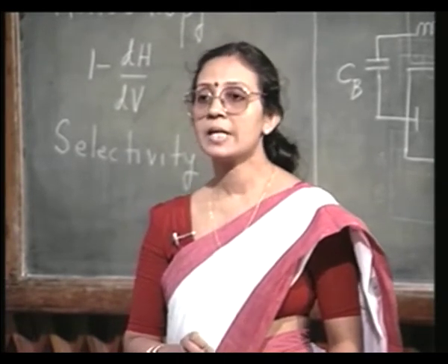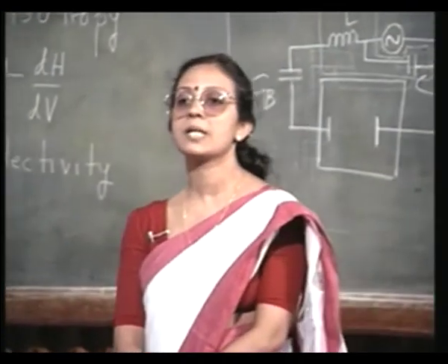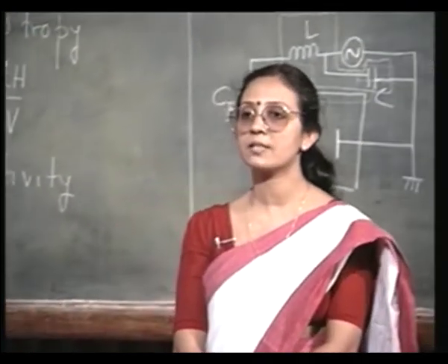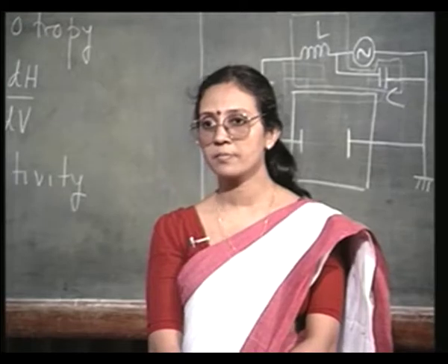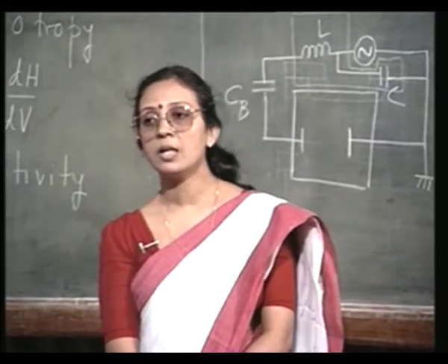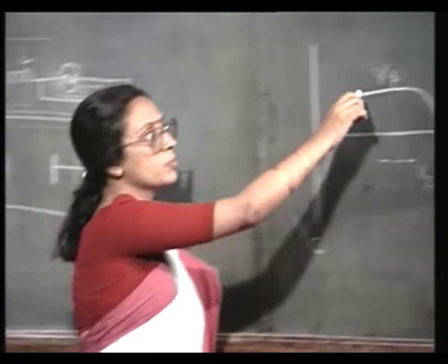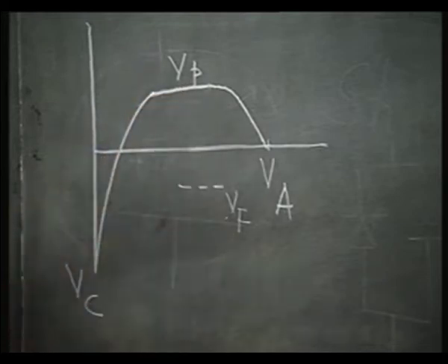If my substrates are placed on an insulating surface inside the plasma, the voltage difference is going to be Vp minus Vf, and Vf is negative. So, actually the magnitude of this potential is larger. But even then, Vf is a small negative value.